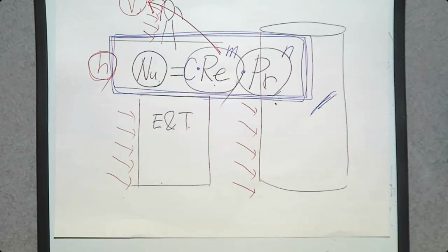What is the other half of the problem? Once you determine H, use the governing equations that we studied in chapter 3 and chapter 5 to determine the unknown temperature T or the rate of heat transfer. So basically, you already know half of how we are going to solve the problems. One thing that you do not know is H. So we are going to study how to determine H, and once we know the H value for this convection problem, then you will use either the thermal resistance network, fin analysis, the lumped method, or approximate method. That's how you are going to solve them. Okay?